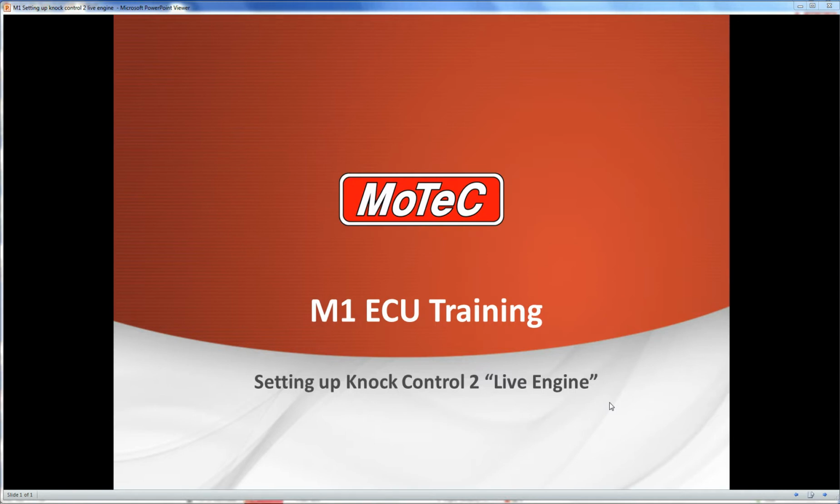If you're watching this webinar, you should have seen the other two already. There is one we did on setup of knock control just in the software. One previous to this one, which was on a running engine, where we did basically set up the frequency and looked at determining the best center frequency for the engine. And on this final one here, we're just going to look through on a live engine on our M1 Tune software at the retard working and just make sure the system's functioning correctly.